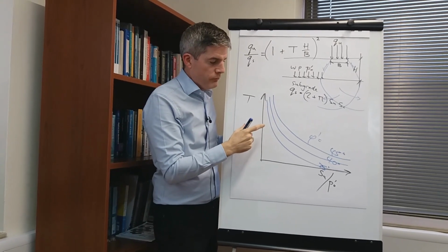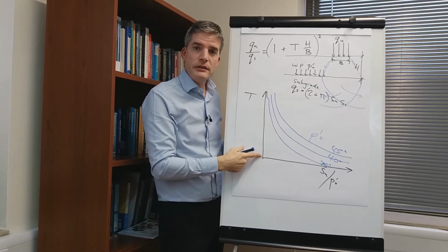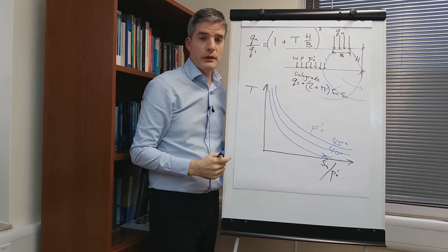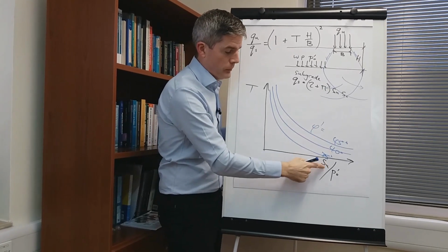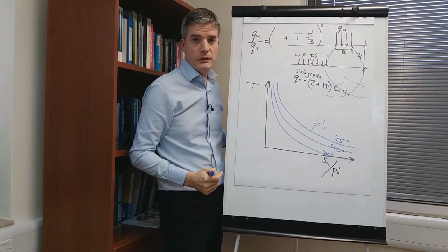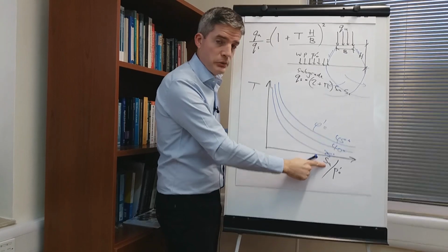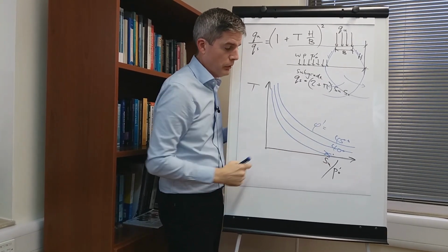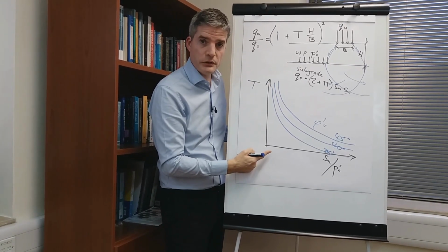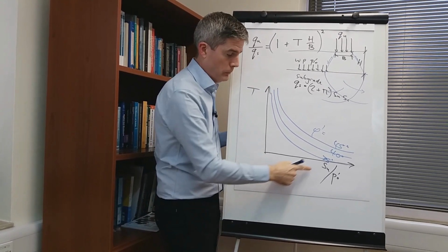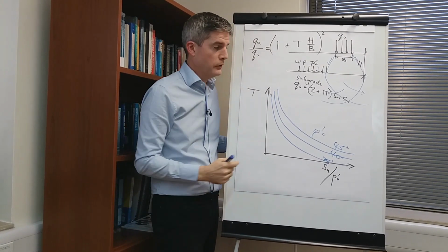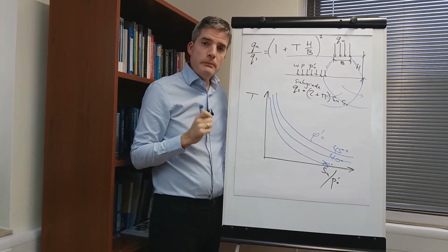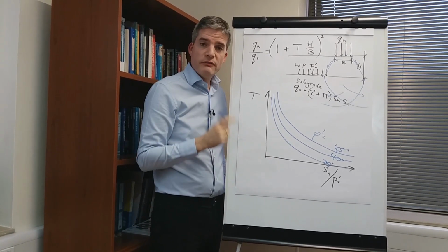So it's a very simple and easy to use design method, all in one chart and a very simple equation, with input parameters that are familiar and can be determined: simply the shear strength of the subgrade for a clay subgrade and the shear strength of the granular layer. We have also developed a version for sand subgrades, where instead of SU it would be the friction angle of the subgrade. And most importantly, it's all been validated by physical testing.